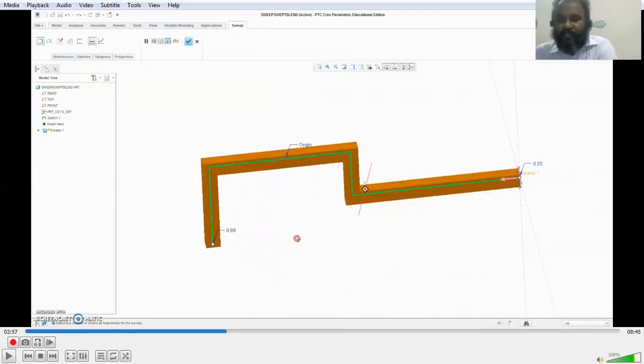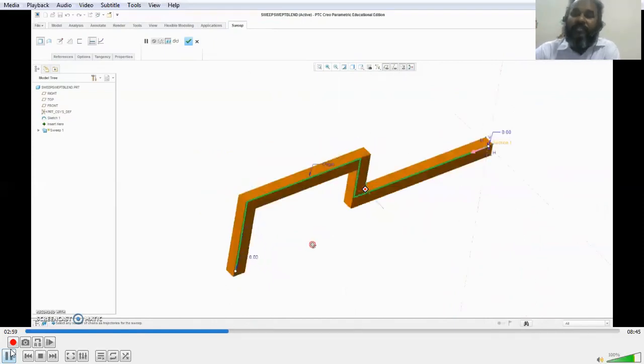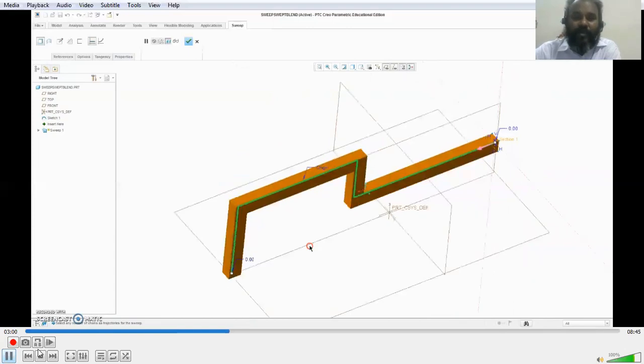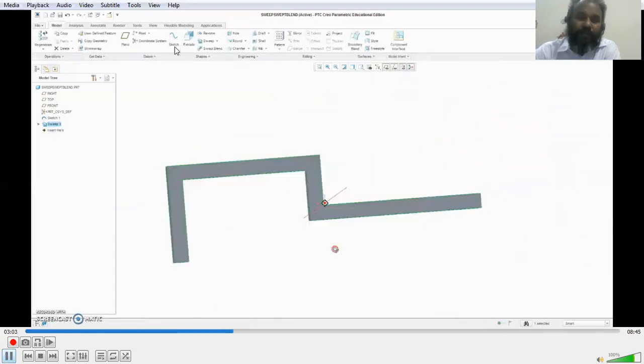So where does the square pipeline come? Say for the chairs, the support structure, the desk and tables, and the frames that go for wooden frame, as a support structure for cupboards and furnitures, and even sometimes the wall like structure can be built with these kind of frames, square frame. So making the square frame is this easy using the sweep option. So once that is done, I put the tick mark for the sweep option also.